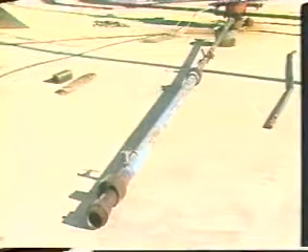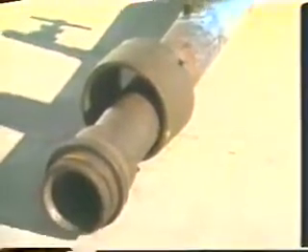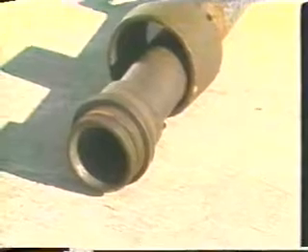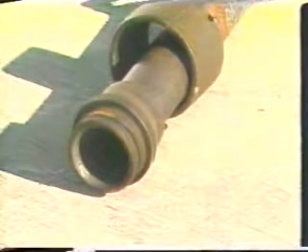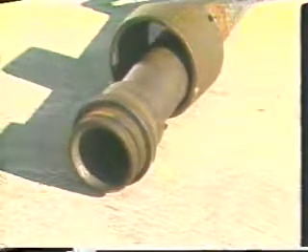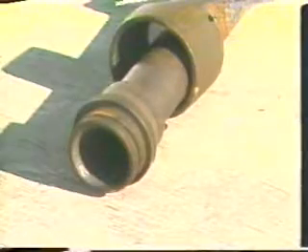The lower lubricator section is normally larger than the upper sections to allow space for the larger diameter equipment that will be attached below the operating tool string. The lower sections of the lubricator must have ports for valves to allow the pressure to be released from the lubricator when the lubricator stack is to be lifted off the wellhead. The lubricator, stuffing box, and wireline valve normally have quick union connections for ease of assembly.